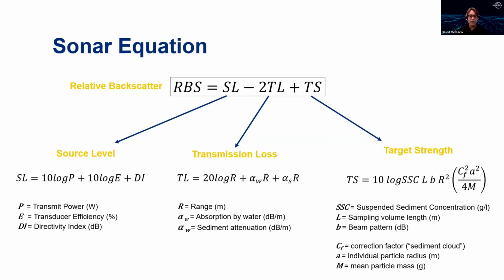Now, later on, all of this is rearranged, and we want to solve this eventually for the logarithm of the suspended sediment concentration. Finally, I just wanted to note that target strength here is a parameter that is probably one of the main reasons why people who have been using the same ADCP and going back to the same location time after time have actually been quite successful at using ADCPs for sediment work.